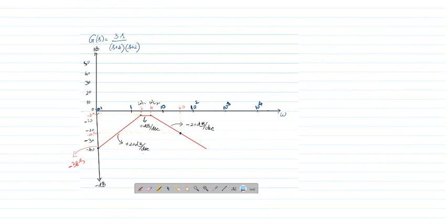Let us see that this is the transfer function we have, right? How many factors does this transfer function have? This is a constant, right? Constant. This is a zero at origin. This is a pole at minus 4. This is a pole at minus 2. Among these four terms, which are the terms that function at all frequencies?